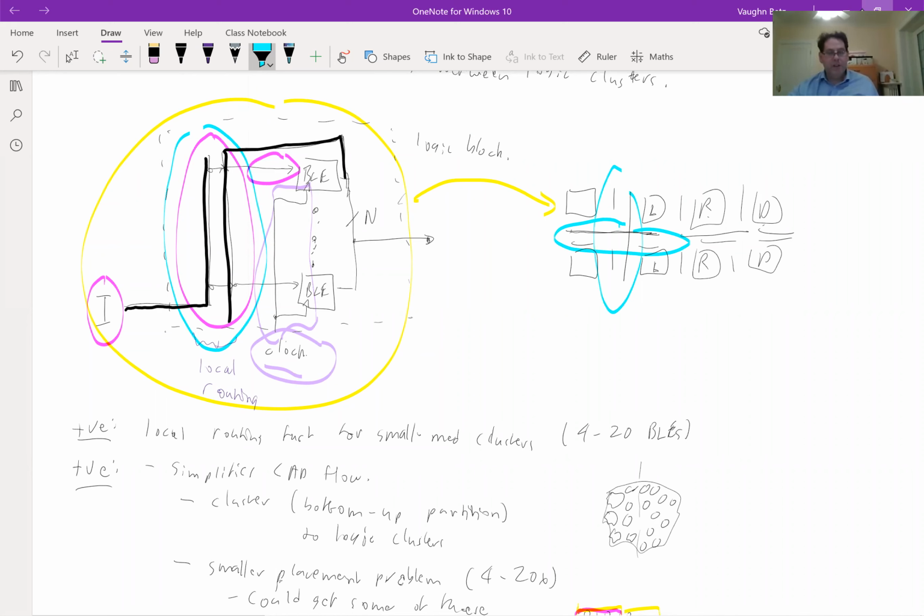The two biggest FPGA vendors are going in opposite directions. They're both using the concept of logic clusters, but Intel, in their absolute latest chip, is making the local routing more complicated to deal with R and C, which makes the abstraction of a nice simple hierarchical FPGA a little less true.